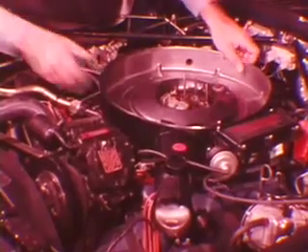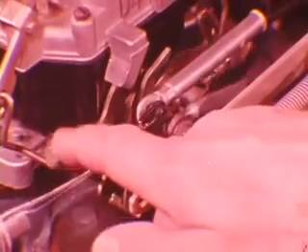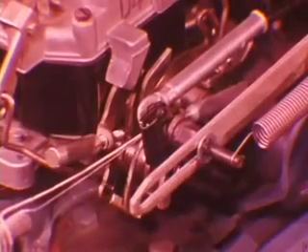When the analyzer finishes code 6, it might go either to instruction code 7 or 8. Let's see why. Code 8 is actually a special code which appears only if the throttle position transducer is out of adjustment. When you adjust it, be certain the throttle is closed and off the fast idle cam, and adjust the transducer as near 0 as possible.